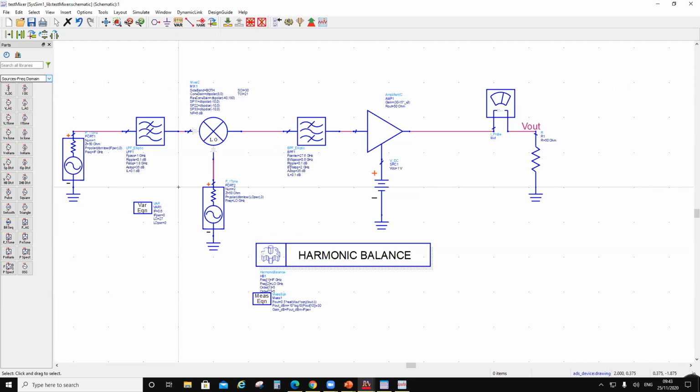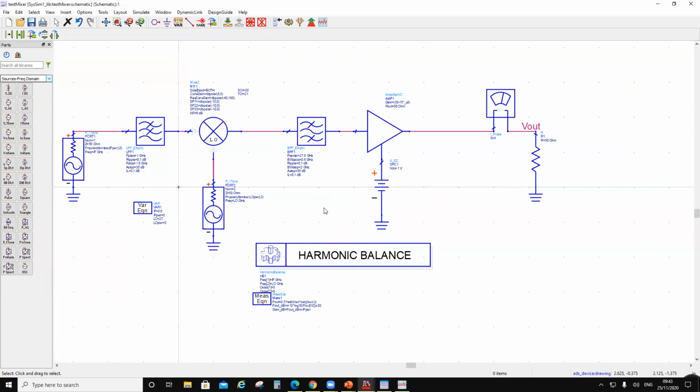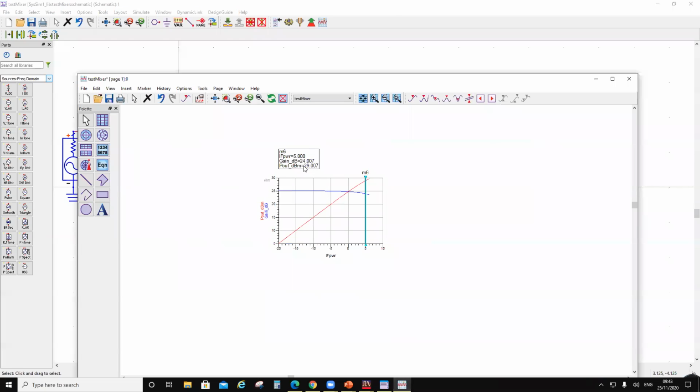Let's see. Again, the culprit would be this only. To start with, you started with 0 actually. If it was 0, that was another story. Now let's say 7.5 over here and 15 over here. So it should be 22.5, that should be the gain. Rather, I'm getting 25.